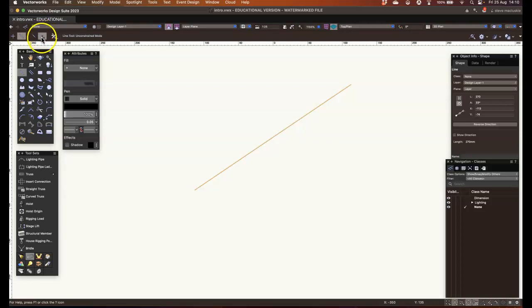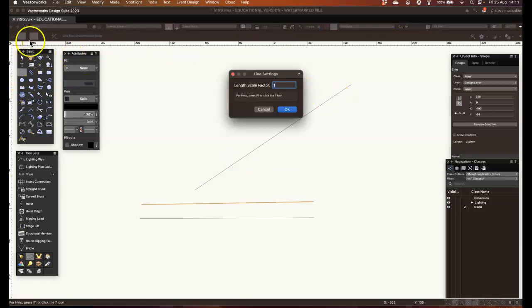mode within the lines is the center mode. So if I'm drawing a line, normally it's end to end, but the center is quite useful in the theatre, because if I am drawing a counterweight bar, for example, and I know it's centered to the stage, maybe drawing it from the center line of the stage out is an easier thing to do than drawing it side to side and then having to find the middle and move it into position. So just be aware that there are modes there for the lines.